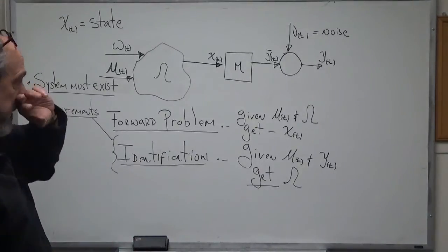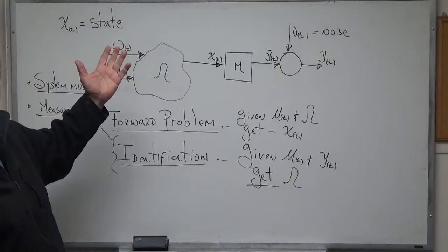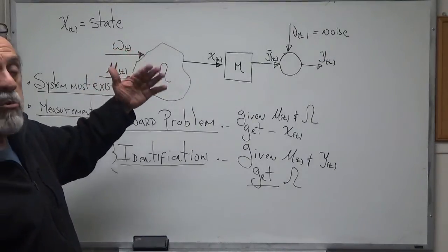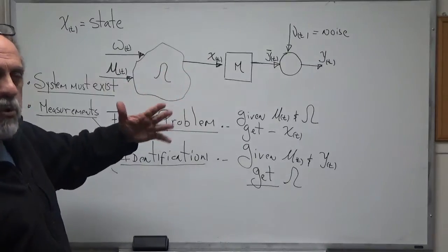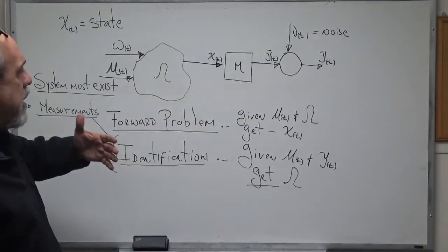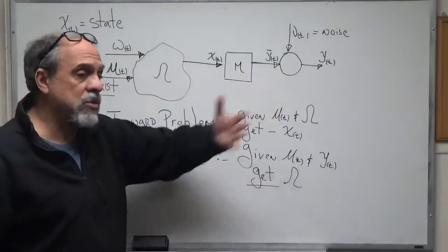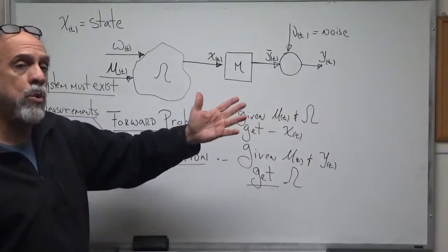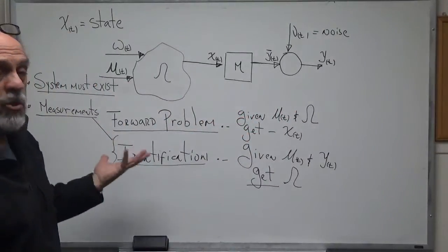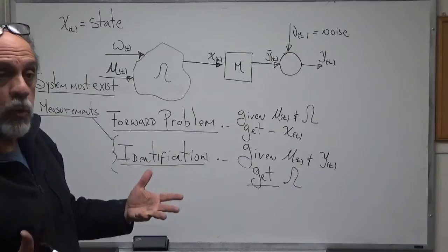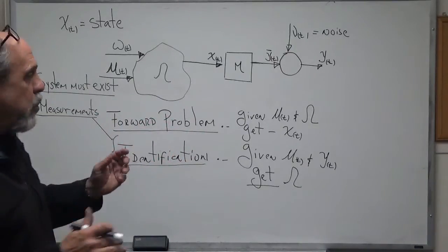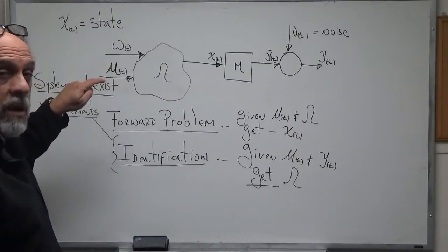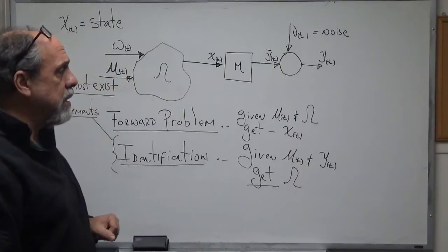A typical case might be a bridge where we want to learn something about its properties, and all we have is the vibrations of the bridge when the traffic is going through, but we cannot measure the excitation. We know it's the traffic going through and some wind and things like that, but we don't have this U as a function of time. We can still learn something.